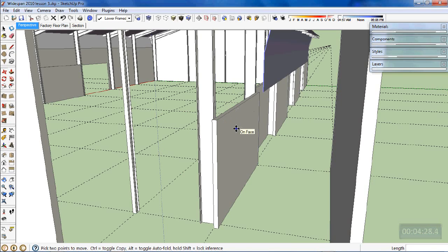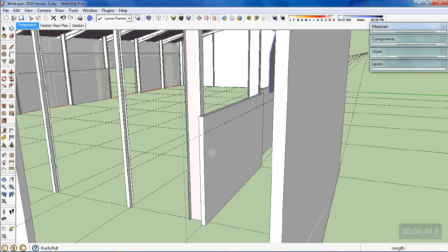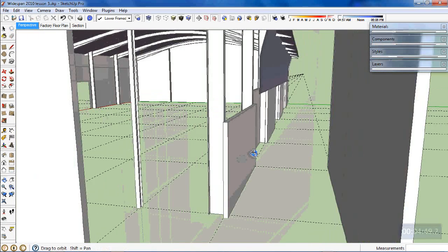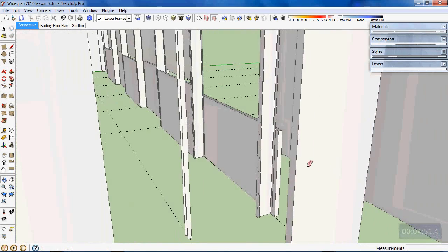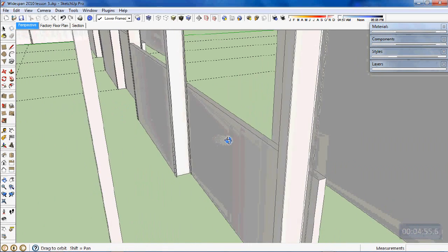So I'll just grab my tape measure and come up from this edge 3080, and we'll pull down to that line. Get rid of that set out line that I've just created to do that. Okay, so that wall then could establish the height so that the floor joist could span across the top of that wall and create the office level upstairs.